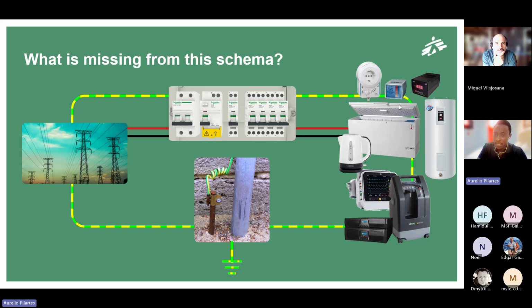It protects you not only against over voltages, but also against frequency fluctuations. So it will keep your frequency at 50 Hertz exactly, and it will give you some backup. So whenever there's a shortage, the batteries will keep running your system. So these are a bit more expensive, as you can expect, and they are meant to protect very sensitive equipment, the UPSs. Most biomed devices are always recommended to be connected over a UPS.